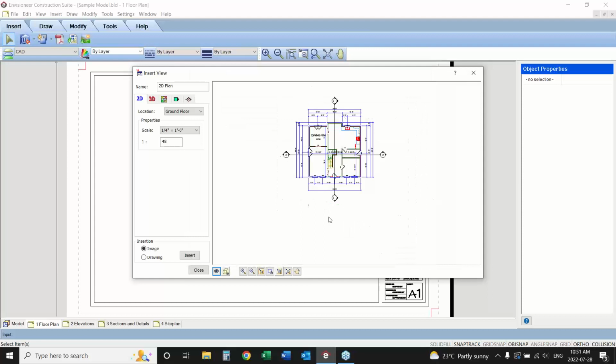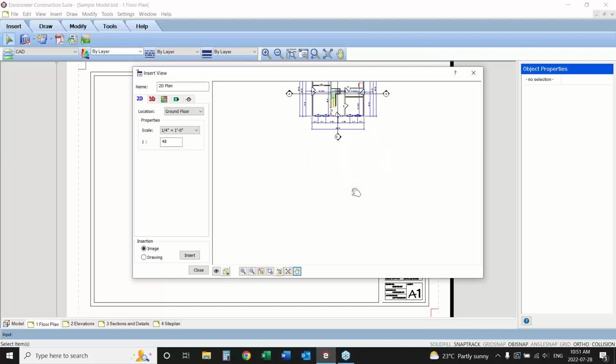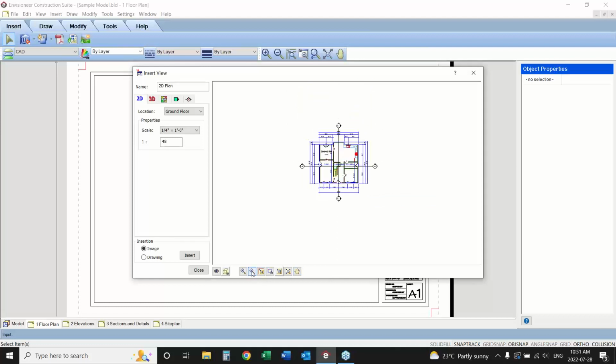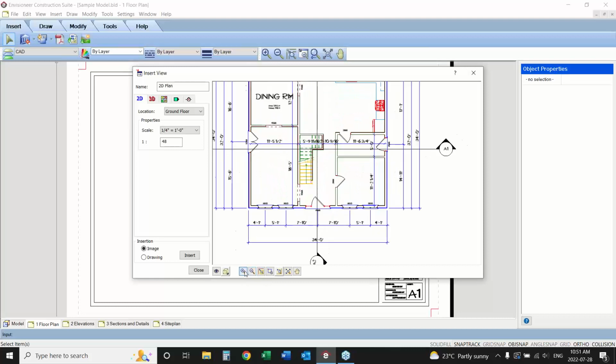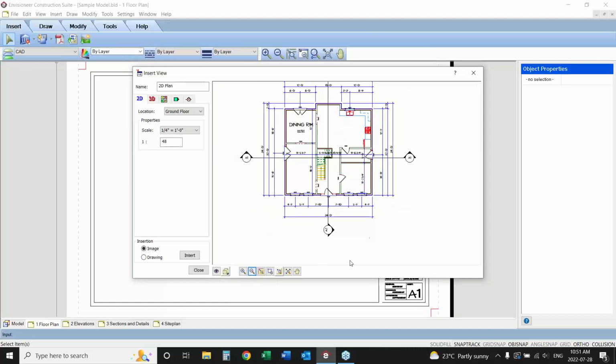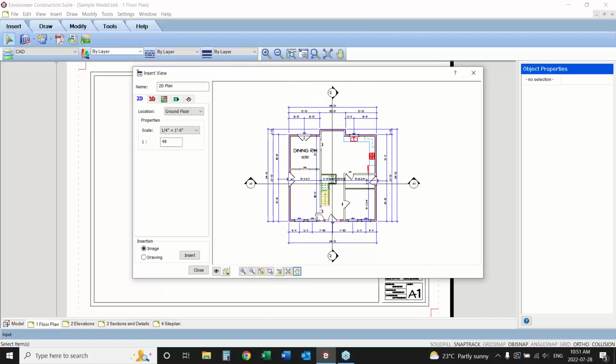That updates the view. Another thing to remember about WYSIWYG, what you see is what you get, is if I pan my model up like this, what I see is what I get. I get a half-cut model. So make sure you can see the entire model. Okay? If you zoom in and zoom out, and I zoom in too much, that's all I'm going to get. So make sure you zoom in so that you can see the entire model. Zooming in and zooming out does not affect the scale.